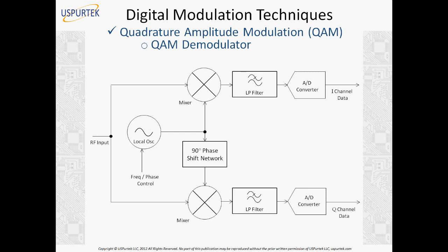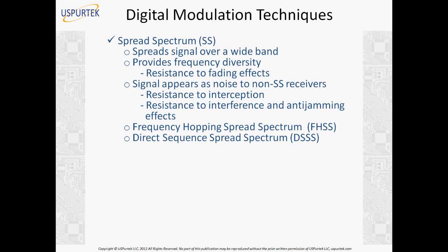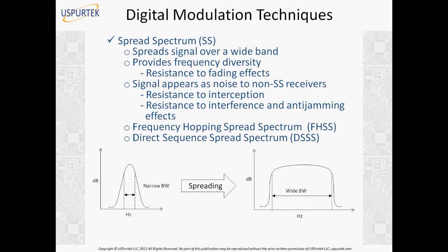Okay. So now let's talk a little more about the spread spectrum technique. Spread spectrum technique has been used in many technologies. Typically, CDMA uses this, and many other technologies also use it. So what is unique about spread spectrum? We spread the signal over a wide band.